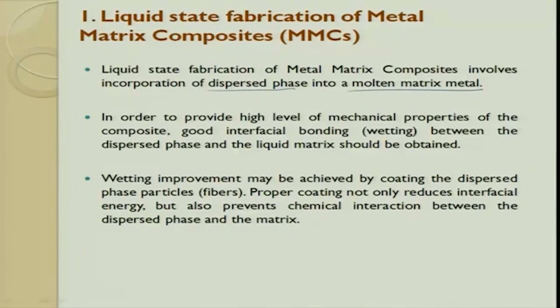In order to provide very high mechanical properties, good interface bonding is very, very important. That's why people look into the surface energy of the ceramic particle, or the basic nature of the matrix. Can these two gel with each other? If they gel properly, then there is a proper interface.